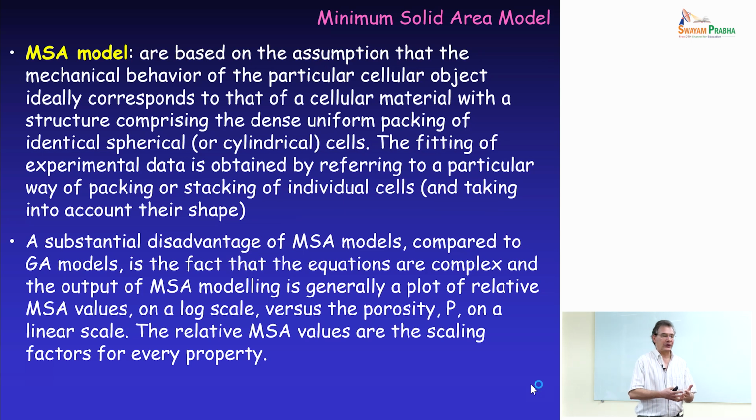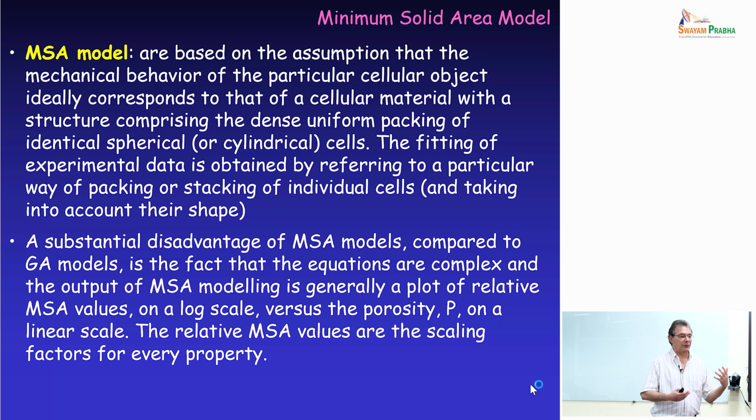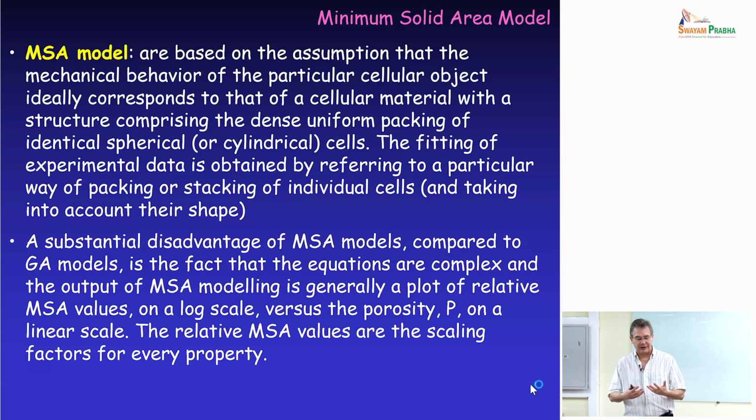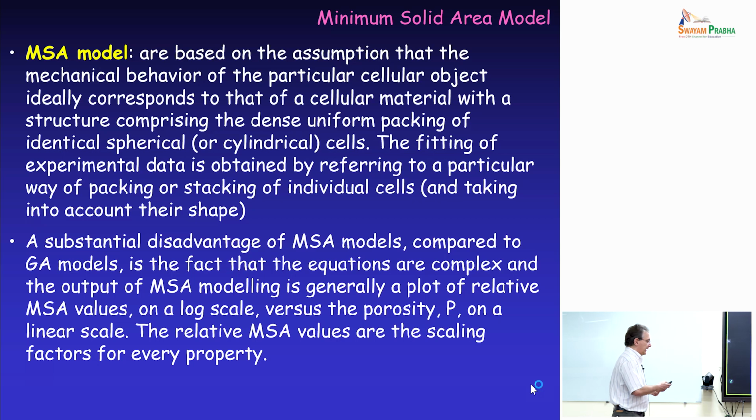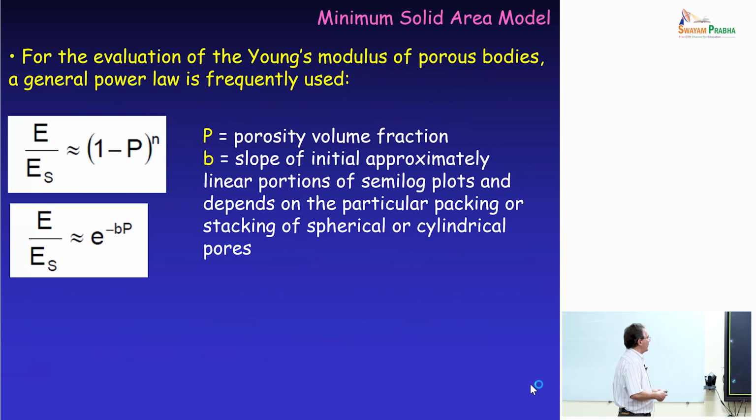And the flaw population of the samples is completely different from the type of flaws that you generate when you do foaming, for instance, or when you process a highly porous material using a different approach. So sometimes this approach doesn't allow you to have proper modelization in terms of values for the behavior, but the trends are correct. I don't need to spend time to discuss the other approach. Simply, these formulas give you relations between mechanical properties, elastic modulus, flexural strength, compressive strength, and porosity.